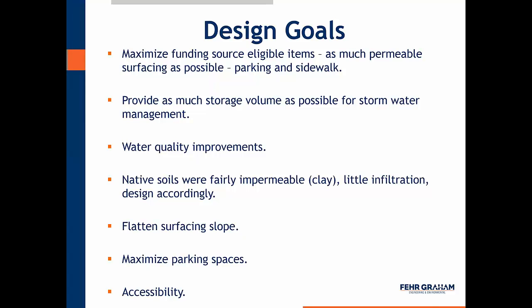Talked about the driveway being very steep. Also, the parking area was very steep, 7 to 8%. So, you guys that are familiar with steeper areas, it can be a little unpleasant. So we were looking at flattening that slope out as much as possible. We talked a little bit about the unorganized randomness of the parking spaces. So main goal here was to maximize the number of parking spaces within the parking lot footprint, and then also improve pedestrian accessibility, whether it's getting from their vehicle to the aquatic center. We just wanted to make it more accessible.